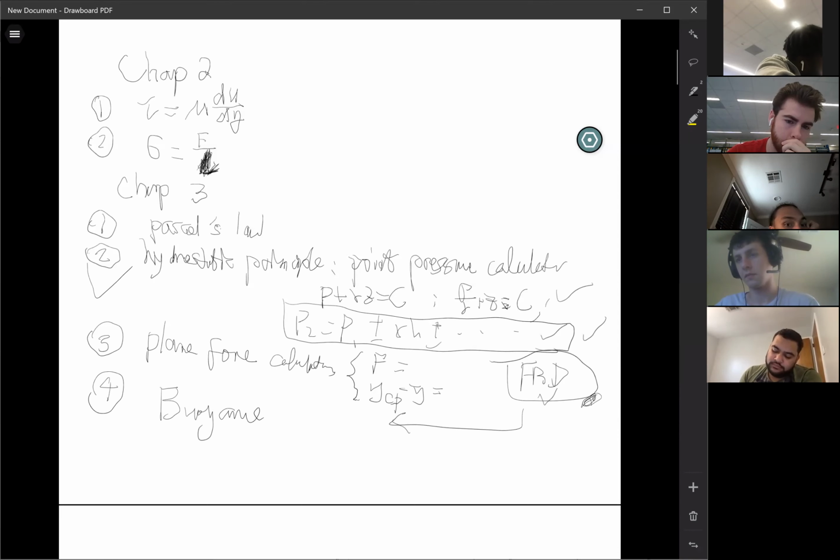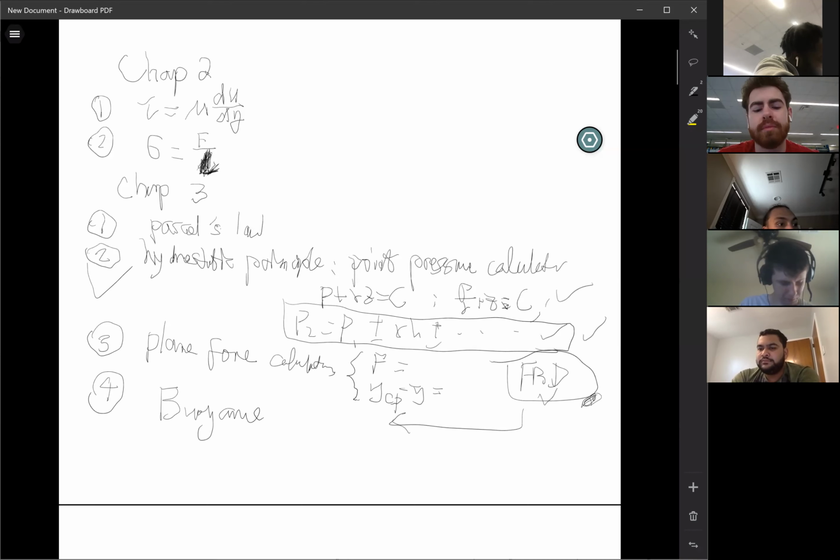If there's a rotation involved in your problem, your first choice may be to use the moment balance equation, summation of moment equal to 0. You need to know a pivot point, then write down the moment equation. Again, the free body diagram has to be correct. If it's not, then no hope. That's why a lot of students score really low in the static class, because if your starting point is not right, then it's a problem. I extremely want to focus on the free body diagram in those static problems.